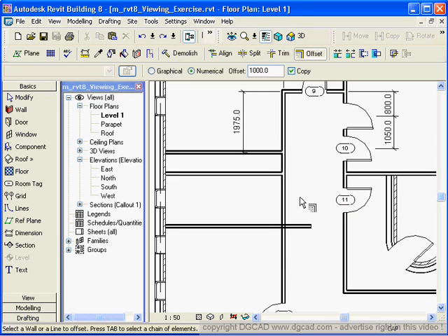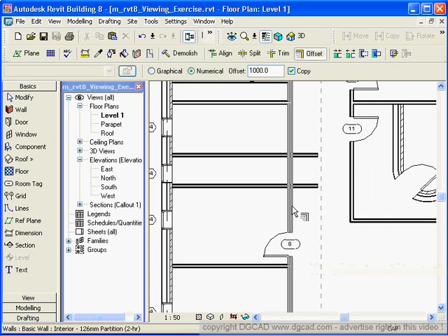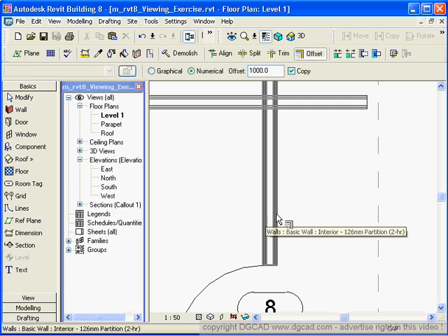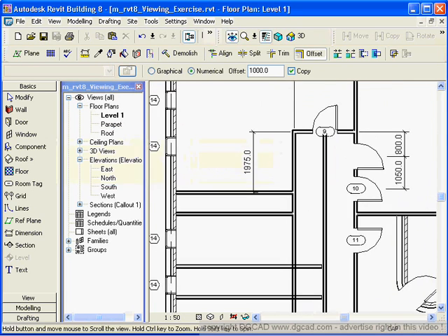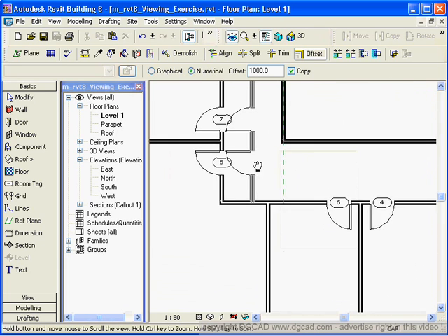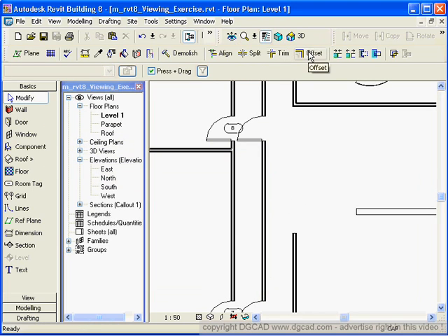I'm not worried about deleting those ones. Okay, so there's that type of trim, and then there's the offset command, which basically you can say okay, offset, and if you click on this, it'll actually offset whatever it is, that wall, by that distance by typing in a distance over here, and depending on the surface edge you pick will depend on where it goes. So we can use our offset command, and again it looks like it's found a problem up over here or down over here. So we're noticing that we're getting all those little warning signals. So we've got our offset, we've got our trim, which is giving us our different options.